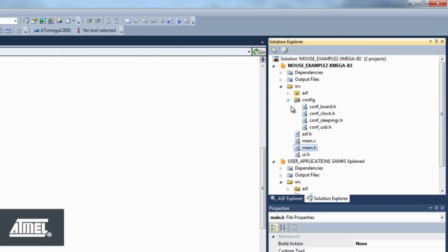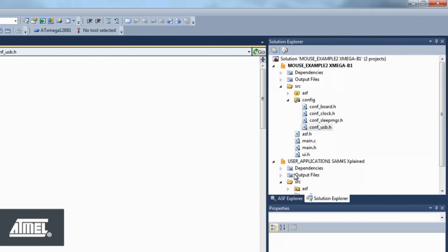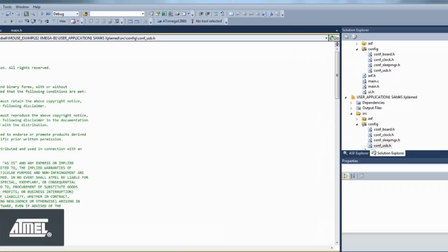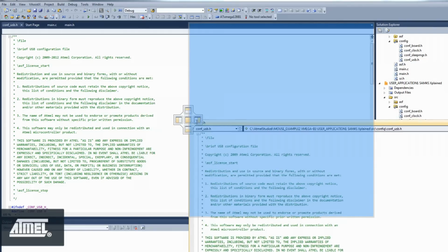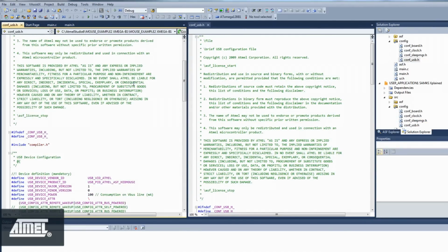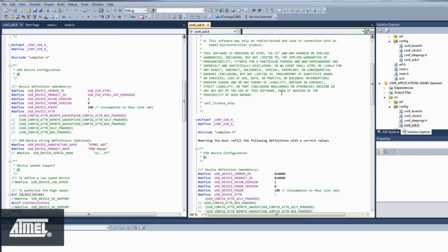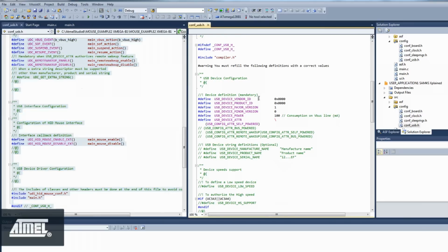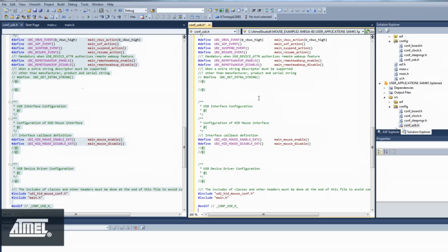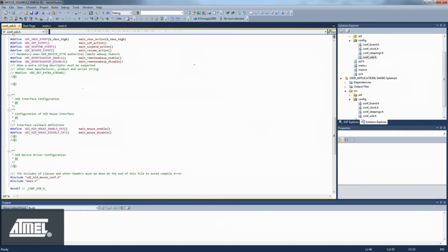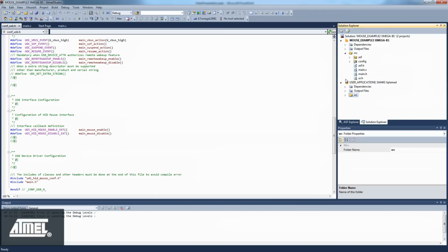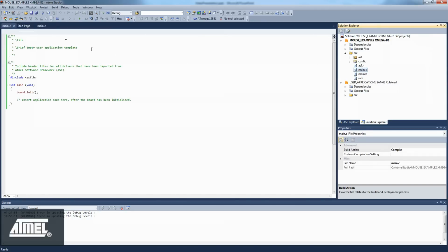Once we have added a service or driver to ASF, the next step in our process is to modify the relevant configuration files according to our application requirements. These will be the same between the Xmega and SAM4. In our Xmega application, we made some modifications to this file, so we directly overwrite the default file in our SAM4S project. conf_usb.h is the glue between the services and application layers, used to link the USB driver to the functions in our application layer.